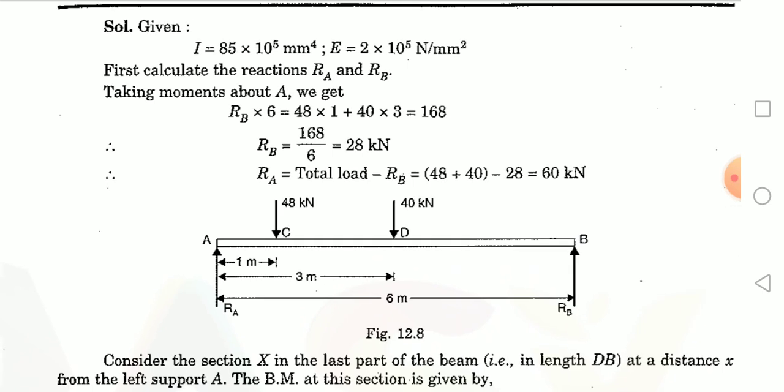Okay, so I said clearly in our class that if the problem is having a simply supported beam with the central load only acting, then we can do it by double integration, whereas when there are multiple loads offsetly acted on the beam, then the problem is tedious to get a solution. In this case we can use Macaulay's method to find out a solution.